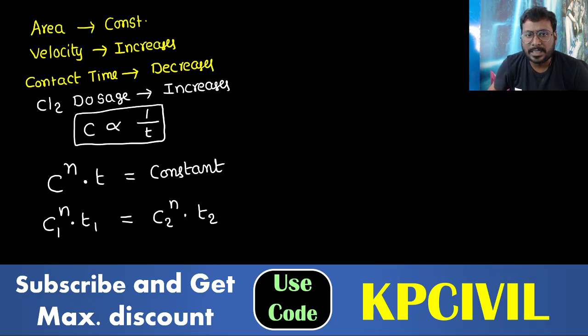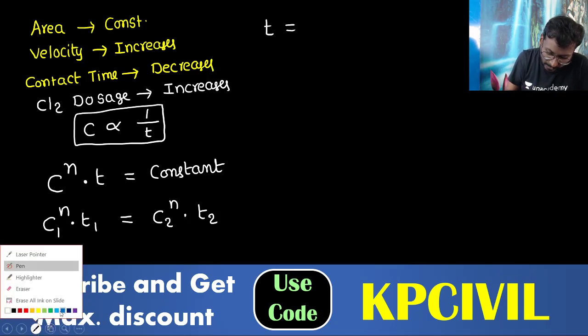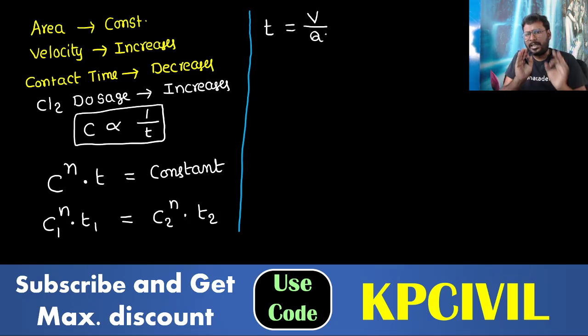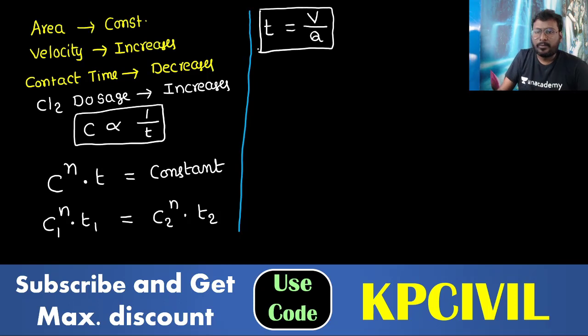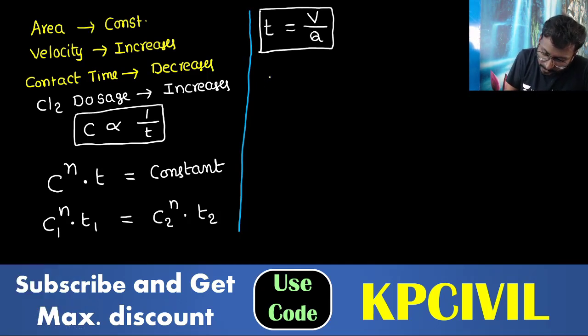What is the formula for time? Is there any information about time? We'll take the general formula for time. For any environmental engineering question, if you need time, you remember volume by discharge, V by Q. Any time, contact period, detention period, retention period, you take time is equal to volume by discharge. Now we'll apply it.